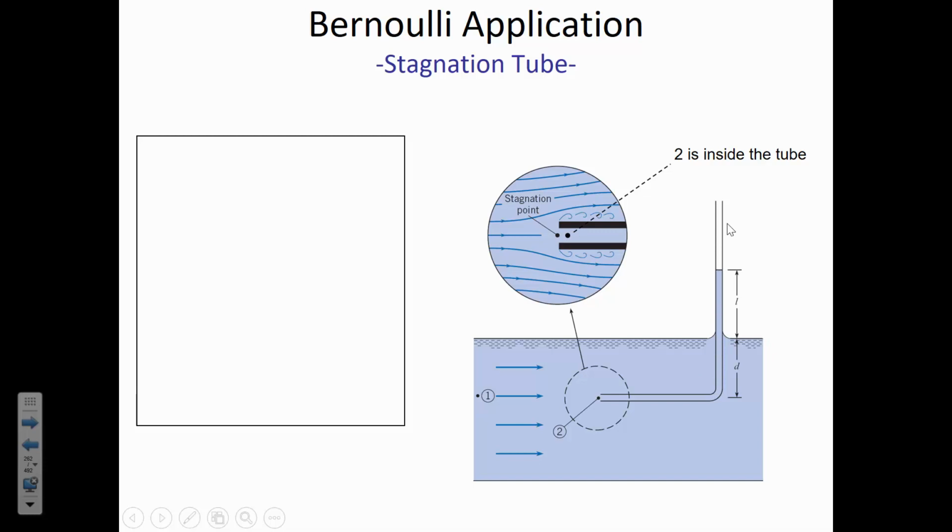What we know is that conditions in that tube are static. The water level, as the velocity increases, is going to start equal to the surrounding water, but as the velocity goes up, this L will increase and then it's going to reach an equilibrium. And this can be explained by starting with the Bernoulli equation applied between 2 points that are on the same elevation. And so they have the same elevation between 1 and 2, and so we've just taken the z term out of Bernoulli's equation.